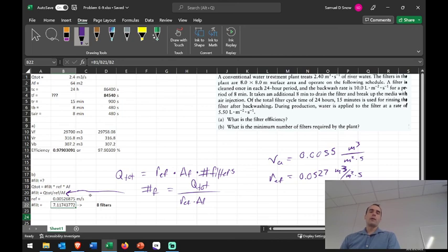And then that extra space gives us capacity to increase our amount of production if we had to, or at least have more built-in downtime available, right? So that's kind of the situation there. And like I said, most facilities will design with the idea that sometimes you might have to clean out an entire filter. It's very rare to replace the media, but maybe they expect to every 20 or 30 years or something. Okay, does that make sense? All right.